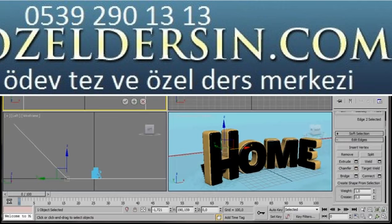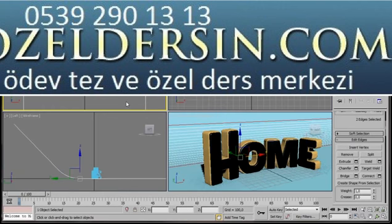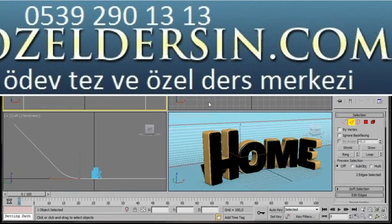Now we're just going to scroll down to the chamfer tool. And here in edge chamfer amount, we're going to type in something like 90. And in segments, let's bring it up to 16. That's given us a nice curved edge, very good. Let's go back over now and click on editable poly to turn it off.